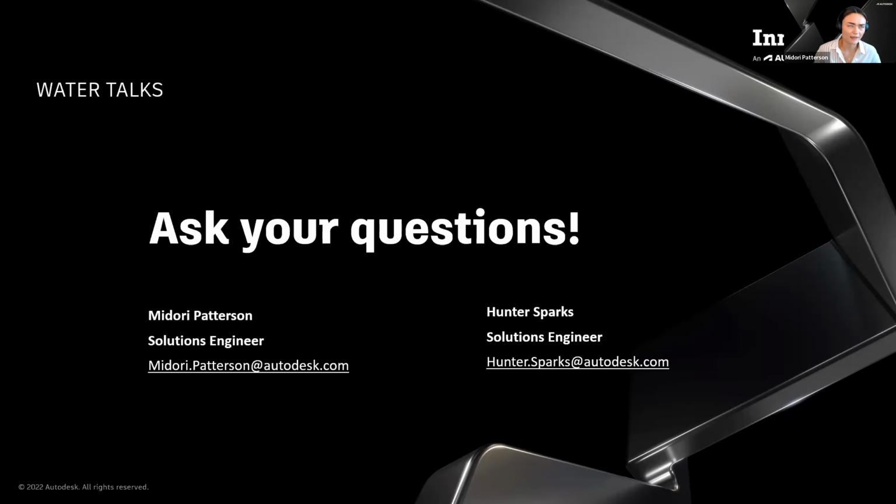As far as I know, there's not a routine in InfoDrainage to load an ICM model, but they're kind of meant for different purposes, where InfoDrainage is more at the site specific scale, and InfoWorks ICM is more for the entire watershed. So bringing an InfoWorks ICM model into InfoDrainage wouldn't be super advisable.